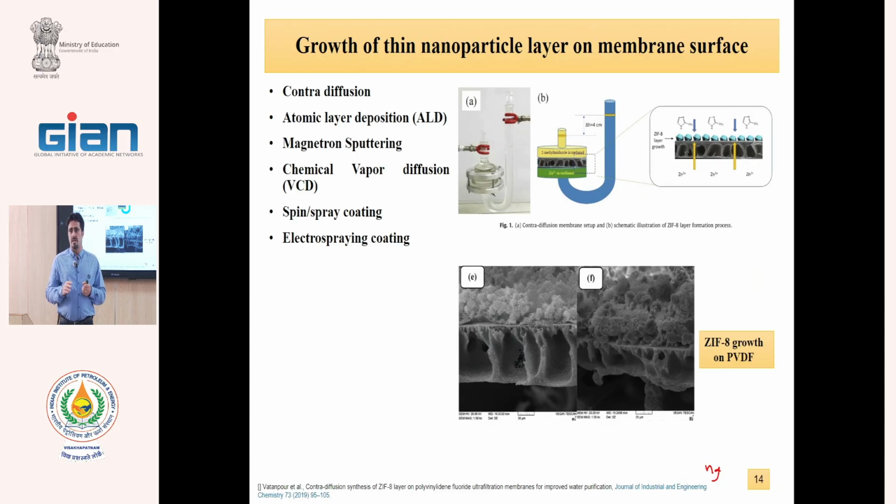In magnetron sputtering, because we have a magnetic field and also an electrical field, the magnetic field causes very, very uniform deposition or growing of the nanomaterials on the membrane. So yes, uniform dispersion is very important. And when we have one thick and one thin layer, it is close to brittle for the membrane,